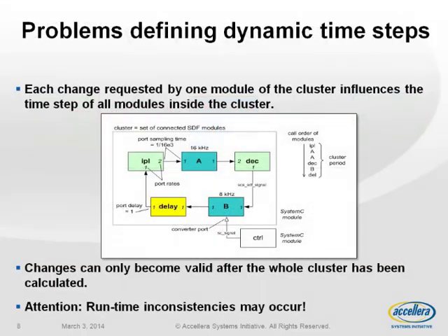This imposes two restrictions. First, all the modules in a cluster have to flag that they are able to deal with varying time steps. And the second is that the execution of the cluster schedule has to have finished before you can change the time steps. So you always do changes in the attributes of the TDF cluster at the end of a cluster execution, because otherwise you would not be able to guarantee the consistency of your model.